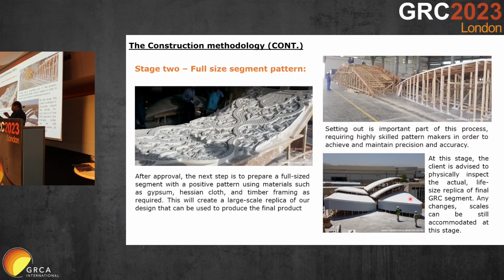The important thing is to get the side flanges at the right angle. Otherwise, they don't match, because you need a good amount of side flange to make the segments stable and strong enough. So the angle of the side flanges is very important.